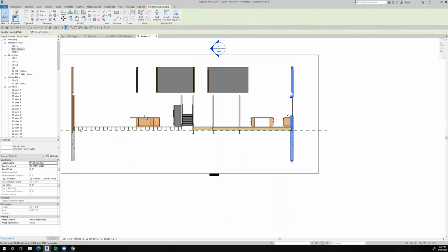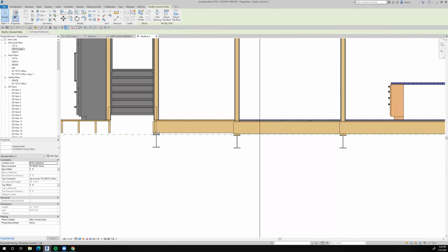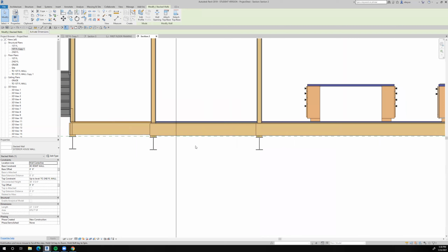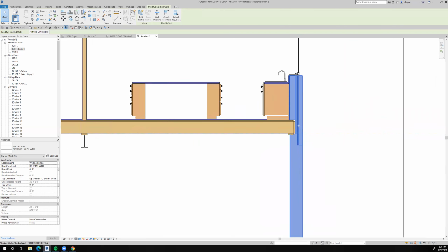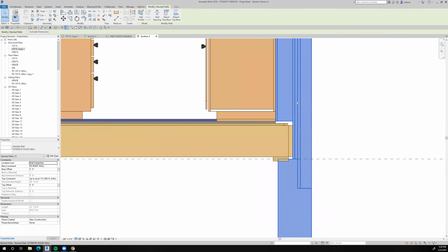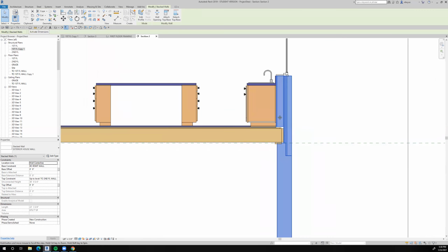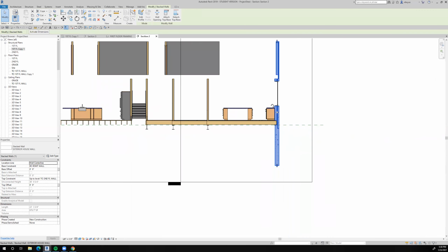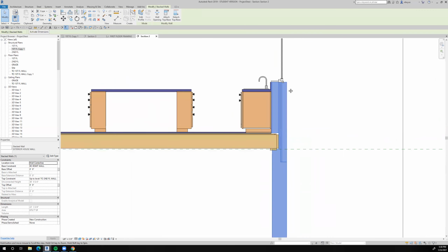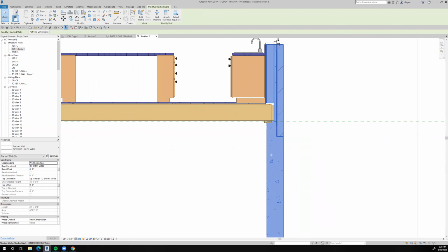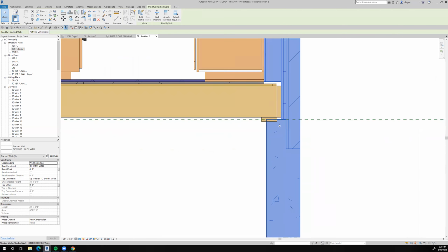But really, right now, everything looks good. We came all the way across. We're seeing all of the things that need to be done are done correctly, except this stacked wall. I'm going to have to add 3/4 of an inch to the height of this first floor wall, and I'm going to have to subtract 3/4 of an inch from this wall, the height of this component of the stacked wall. But we'll stop it right here. It looks pretty good to me so far.